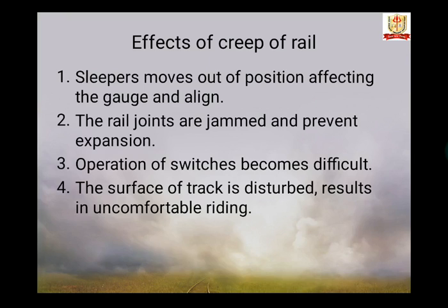Effects of creep of rail. Sleepers move out of position, affecting the gauge and alignment. The rail joints are jammed and prevent expansion. Operation of switch becomes difficult. The track surface is disturbed, resulting in uncomfortable riding.